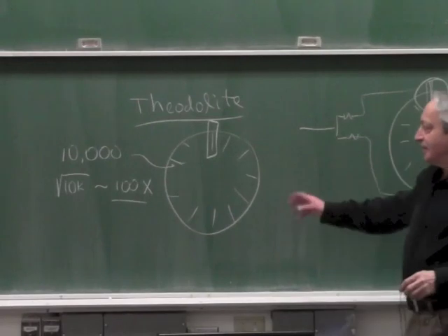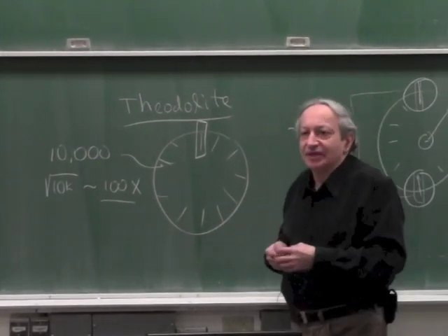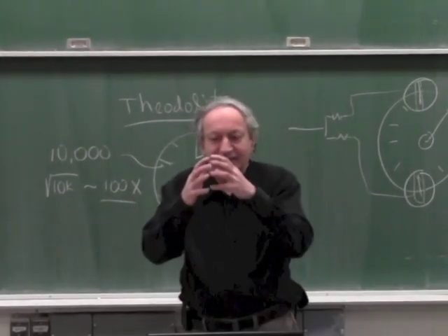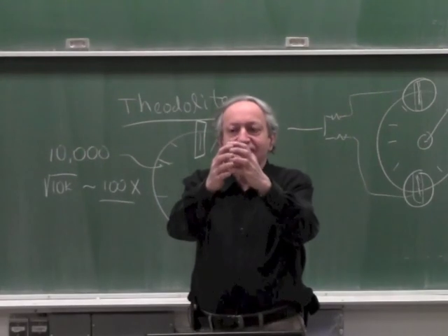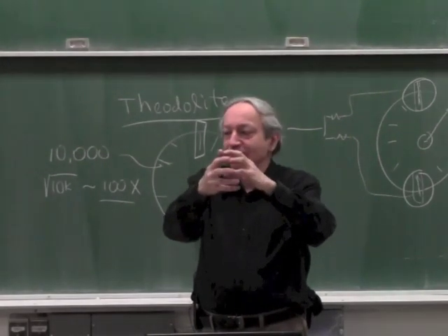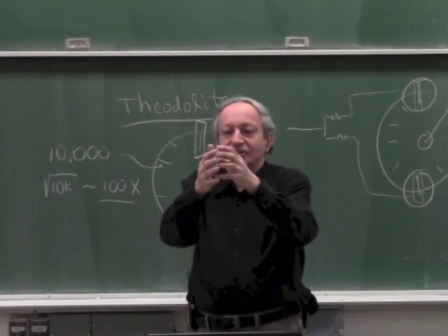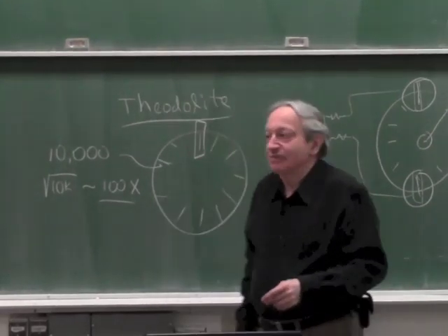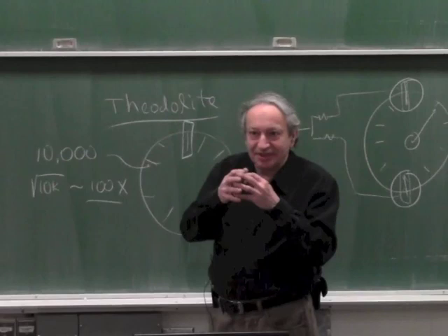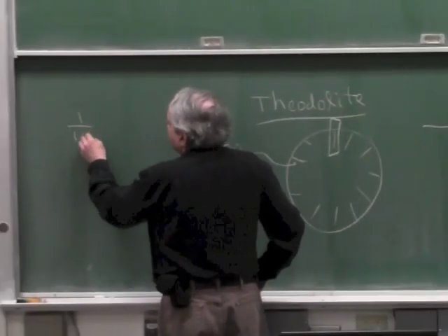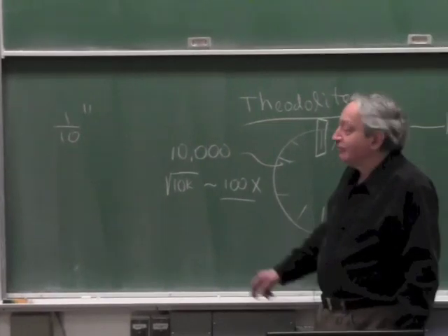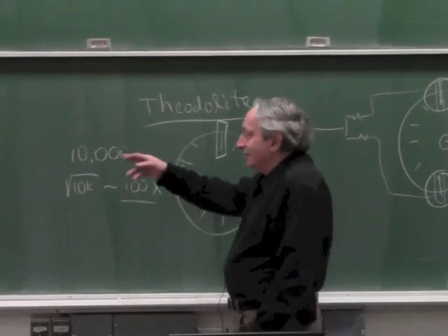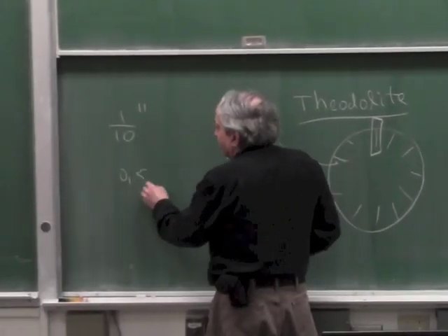I also mentioned that this idea is the basis of the most accurate angle standards in the world, which instead of encoders use two phase gears. So there are two gears meshed like this, and you move them out and remesh them again and again. Typically the gears have 360 teeth, so when you mesh them again and again, they average all the teeth. Using this method, either in an encoder or in meshing disks, you can get to 1/10 of an arc-second accuracy, which is a very, very small number if you start thinking what it means. That is about 0.5 of a microradian.